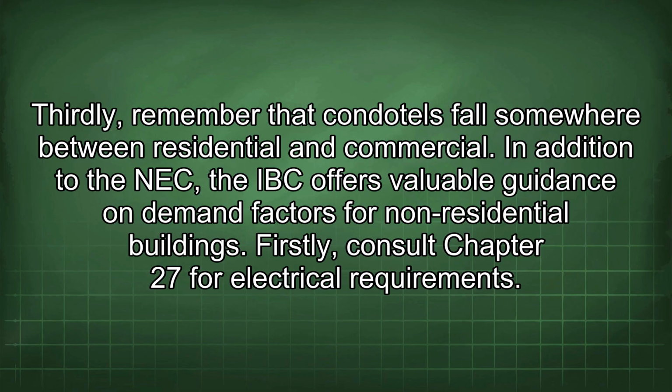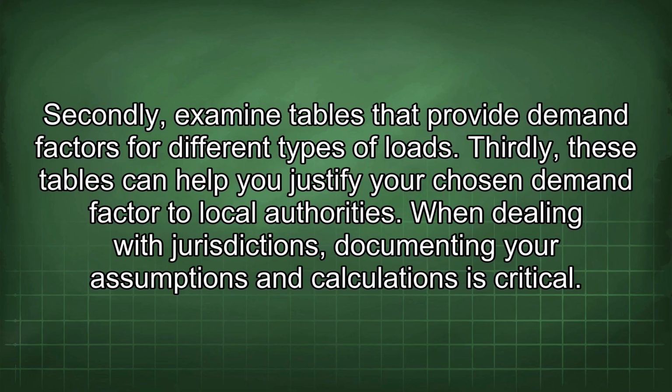In addition to the NEC, the IBC offers valuable guidance on demand factors for non-residential buildings. Firstly, consult Chapter 27 for electrical requirements. Secondly, examine tables that provide demand factors for different types of loads. Thirdly, these tables can help you justify your chosen demand factor to local authorities.